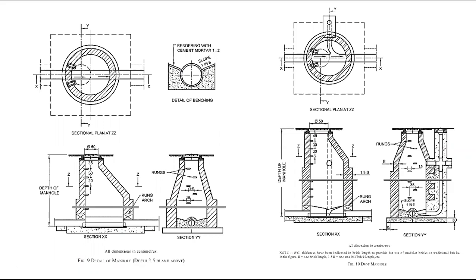For the square manhole, we are recommending it in rainwater drainage and industrial drainage only. If you are using the manhole in sewage, you have to recommend circular shape only. In the circular shape only, self cleaning will be there. Particles will not deposit in the corner.